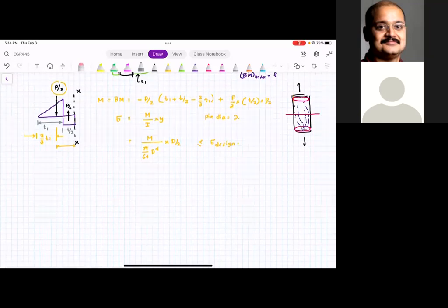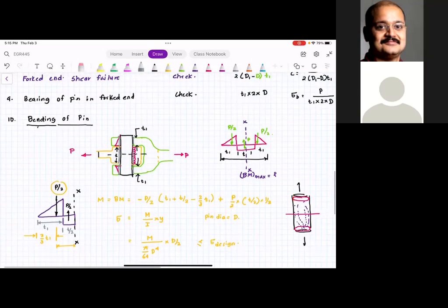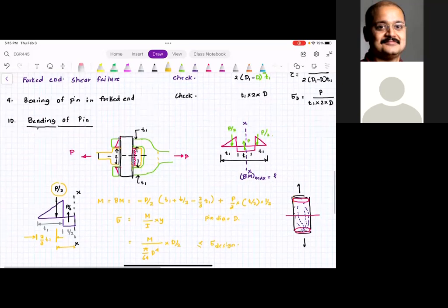If they design the sleeve, do they make it the same length as the rod, or, for example, do they attach them to the fork and eye ends? So here is what I would do if I were to add a sleeve: I would add a brass sleeve over here. It would be pressed into the eye and the fork. So that is how I would do it.